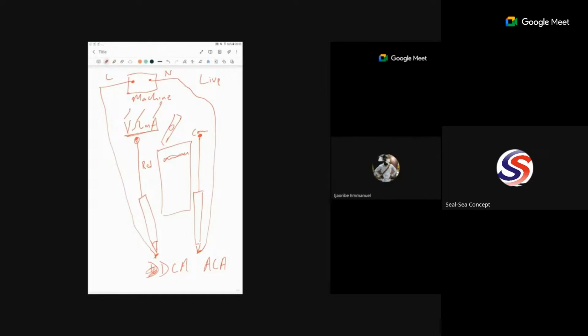And when you are setting your knob, that's your knob, you set it to your ohm. You will see a symbol like this, okay, which is your ohm meter. Okay, you set your knob to that ohms, and with the correct rating, also check it. What is the rating that is there? Is it 50? Is it 100? And you know the kind of resistance you are expecting from the system you want to measure.